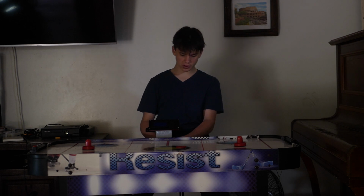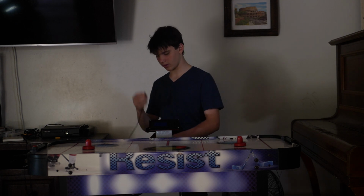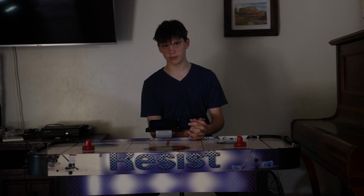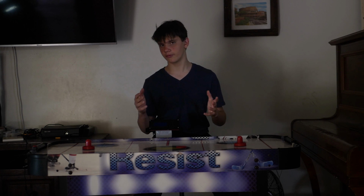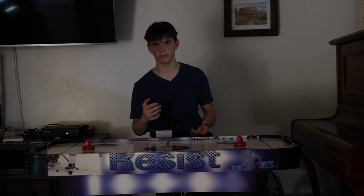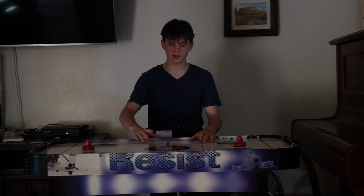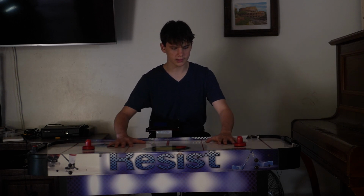There's also a little switch box right behind me, which you'll be able to see on the screen. It's got a switch and a 12-volt input for a barrel jack. The Arduino board in here was soldered by myself with a perf board, and it fits well, but if you've tried to make custom Arduino shields, you'll know that some of the pins don't properly align. So it's a little bit of a harsh fit. There's a relay on here which activates the fan, which blows the air above here and allows the puck to move.